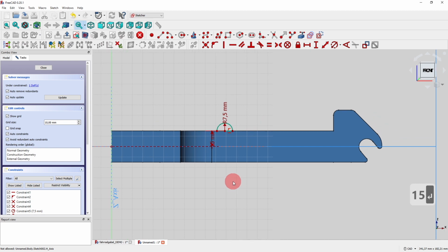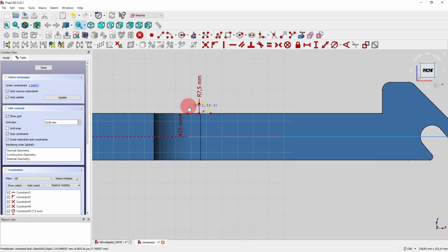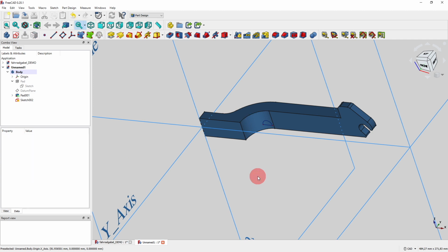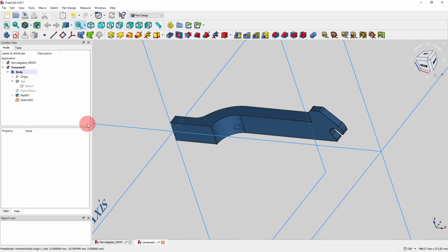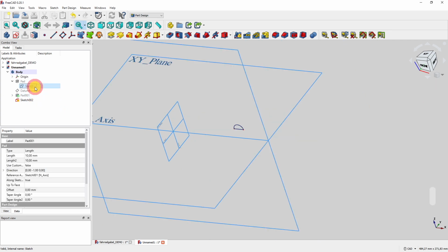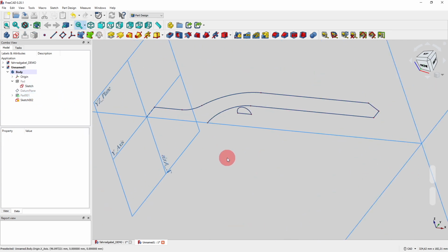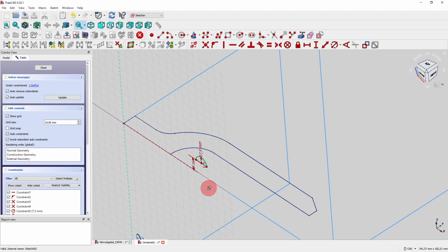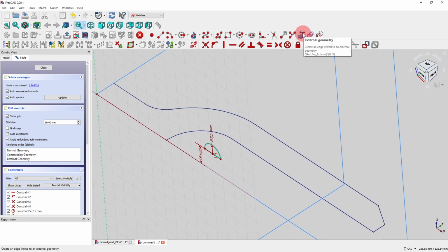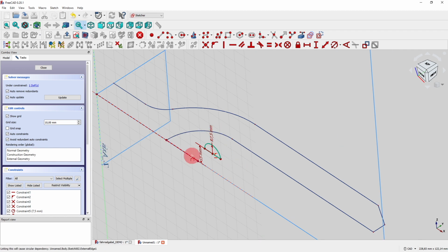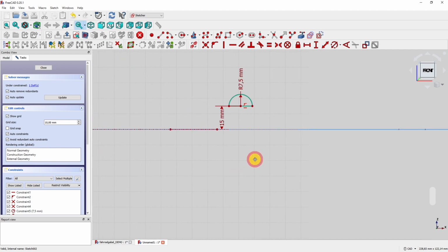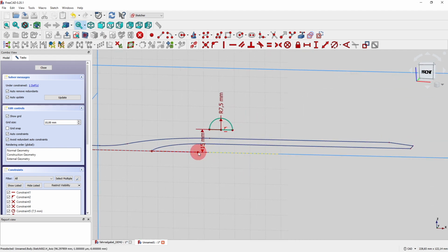All we do not know is the horizontal positioning, because the horizontal positioning has to be relative to the center point of this arc here. You see the problem? It's again a little bit more complicated. I have to hide the pad again, include the sketch here, and then I see the arc here. I go back into the sketch, turn out a little bit, and then I go to external geometry and put this geometry also in this sketch, close, hide this sketch, go back into the second sketch, and now I see the point here. You see it?